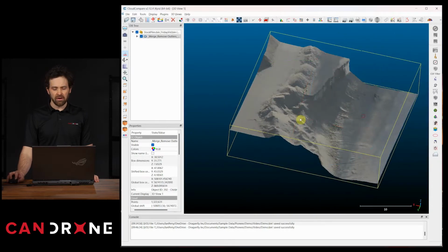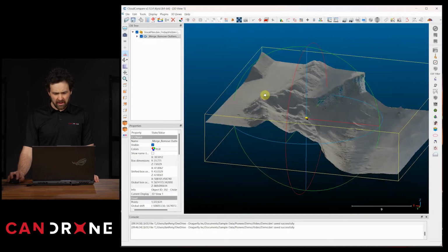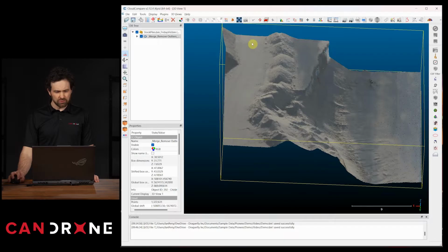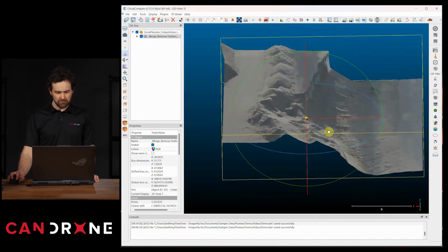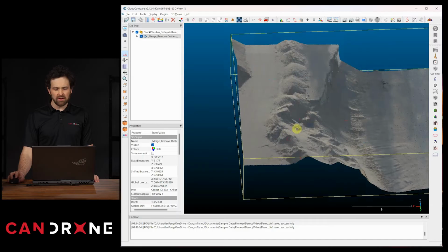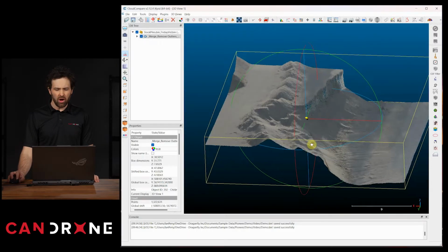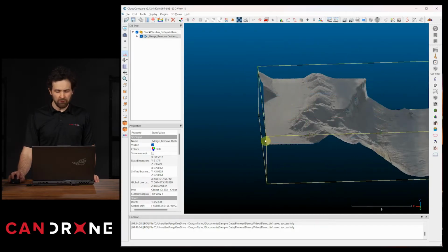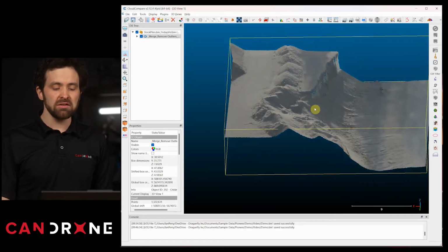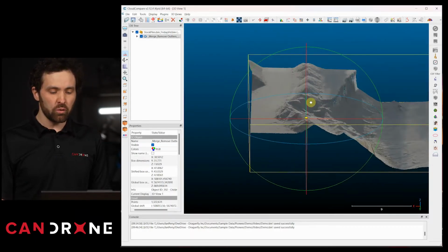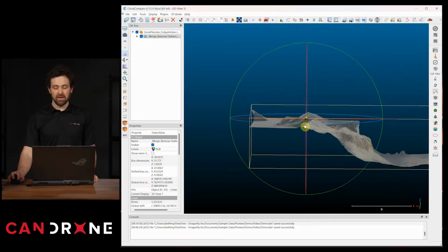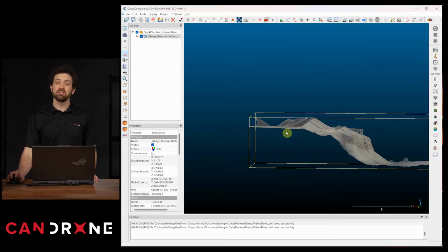So looking at this area, what I'm seeing is there is an excavation face here, and there is actually a road that traverses along the top of this excavation face. Now, we want to continue to excavate here and pull materials off of here, but we do not want to disrupt the integrity of this roadway. That is to say, we do not want this road to collapse. We have to ensure that as we're excavating this face, that we leave a 50-degree slope or less in the excavation face so that this road's integrity is preserved.